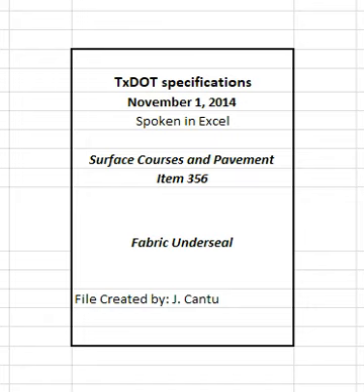4.1.3.1 Transverse joints. Overlap transverse joints by a minimum of 6 inches. Make all transverse joints with the top layer in the direction of traffic if traffic is allowed directly on the underseal. Secure ends of overlapping fabric layer at transverse joints by nailing or other approved means. 4.1.3.2 Longitudinal joints.